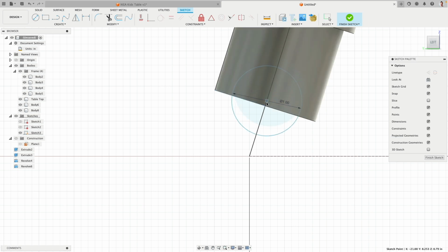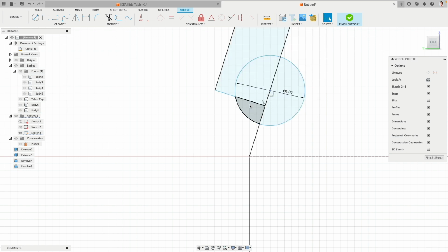What's very important is that the midpoint is above the bottom, because this actually keeps the socket in there. So I will actually try to see if I can constrain this a little bit. So here I have this point, there I have a point, then we add a dimension 0.25 of an inch. Very good. Maybe I move this dimension to here, this one I move to there, so it's a little bit easier to read.